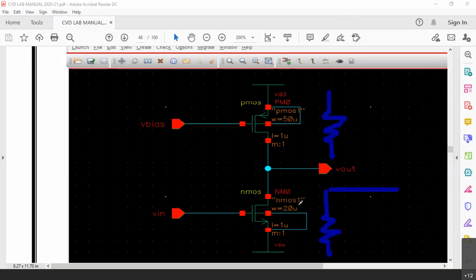That is how these dimensions are decided. This W by L has a relationship there. I cannot tell you more details about it because it is meant for your theory class only. But all these device dimensions have relationships with the functionality of the switch. In that way, this is working like a voltage divider network where this will never go to minus 2.5 because there is a resistor here. That is the answer.